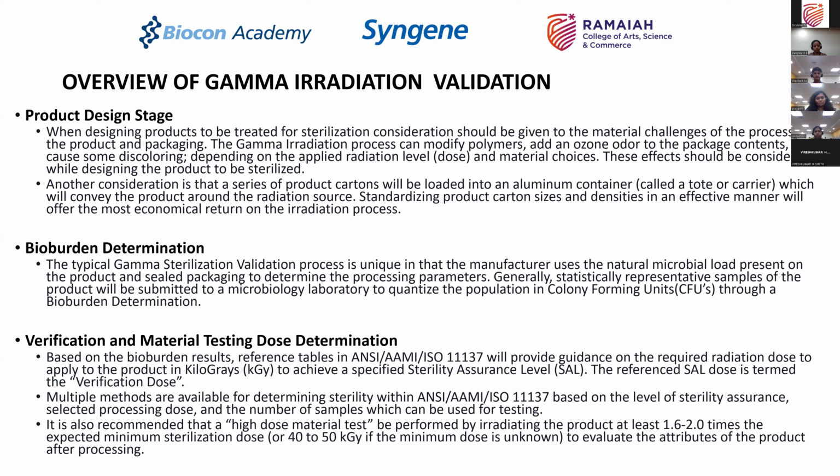So, unlike the bioindicators which we used in moist heat sterilization, in dry heat sterilization, and even in vapor hydrogen peroxide, here the usage of bioindicators is difficult. We could use bioindicators here as well, but what is generally done is that you take the bioburden count of the load through a representative sample of the product which is being subjected to gamma radiation, and then you decide the level of the dosage.